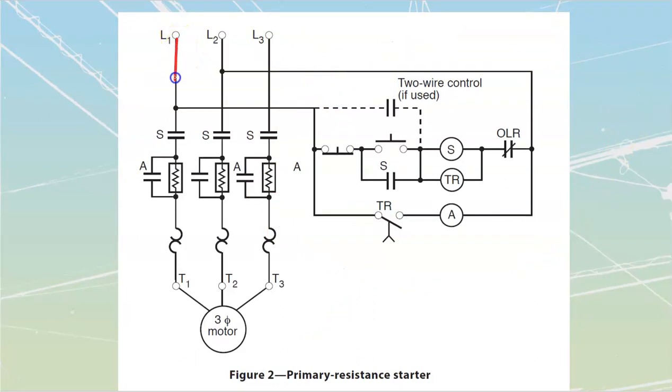The power section is relatively simple. We see that we're going to take lines in through my overloads into the actual motors itself. Once again, the overloads themselves never actually open, but those overloads are going to generate heat that is ultimately going to affect a set of dry contacts inside of here.